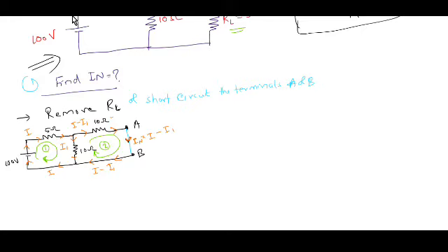From here, loop 1, we can write the equation of voltage. While going in this direction, we will meet the negative terminal of the battery first, this portion. Therefore, we can write this as minus 100 volt. Okay, simply I write minus 100.